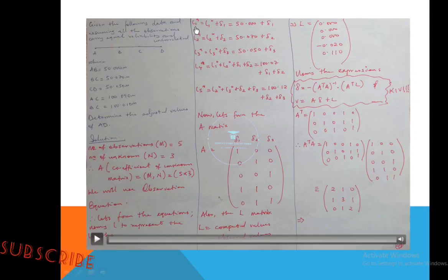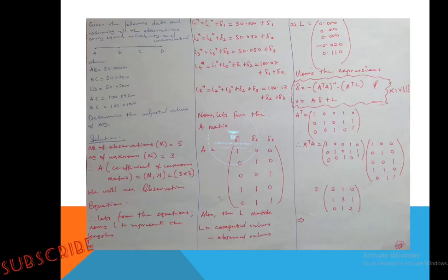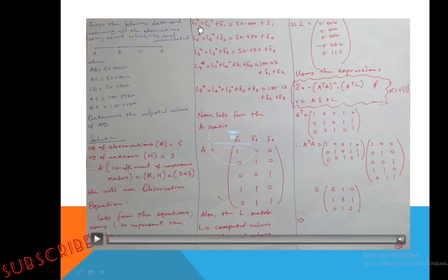Now, before you get the adjusted value of a length, you would have the observed value and the D, which is the correction to the approximate parameter. Are we together, please? We are trying our best to make it as simple as possible. Now the L adjusted, that's the first length adjusted, which is this one. For you to get the adjusted value of this, you need the observed length plus this D.